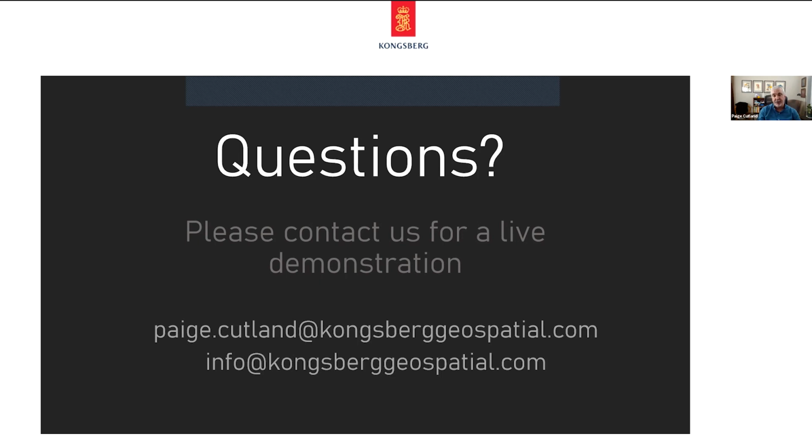I also talked about the Iris Automation. Again, similar situation where you can often have a number of the Casia G sensors to cover something like a city. So again, there'd be multiple areas of overlap where they don't want to see multiple tracks during the flight time through that overlap area. So that's another example of working with that sensor type. And then in general, a common use case for us is where there may be a telemetry tracking service plus telemetry plus ADS-B out from a drone, and they don't want to see all 3 tracks. So we use that prioritization schema to just display a single track, even though they may have multiple sources of position for that drone.